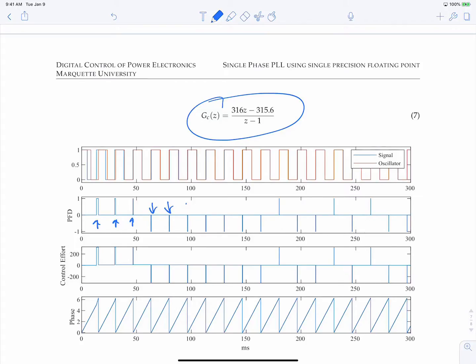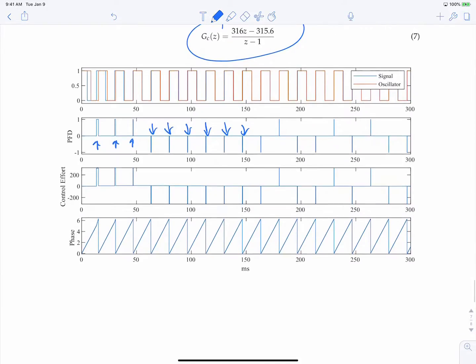So these are some controllers that work. For this type of implementation, I would just stick with the low pass. You don't need the integrator in this case because you have an integrator in your VCO. But it was a useful thing to do here just to see what type of control structures you need for certain types of plants. In this case, there's not really anything to use a PI controller for, and it's actually hard to damp it because you're adding an additional minus 90 degrees on top of the integrator that you already have in your system.